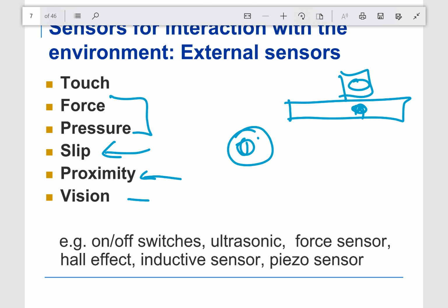So by using LEDs, we can shine red, yellow, green, and measure the reflected light coming back and determine whether or not there are black spots or green spots on a potato chip. And then we can use a puff of air to eject it and say that it's no good anymore.